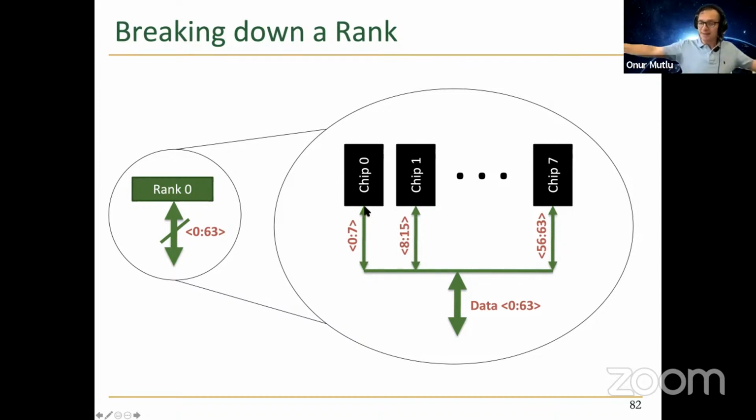So if you want to minimize the cost of a chip, you have only 8 bits outputs. How do you get higher bandwidth? How do you actually construct 64-bit output? Basically, you put eight of these chips together, and you operate them as a rank concurrently. It's like a rank of soldiers. You give the same command to everyone, and every chip responds with different data, essentially. That's how you can actually increase the bandwidth of a chip that has a narrow data bus, as you can see, a small number of pins. Okay, we get 64 bits out over here. Nice. That also increases your capacity, actually, because now you're putting many chips at the same time. So you get both bandwidth and capacity.